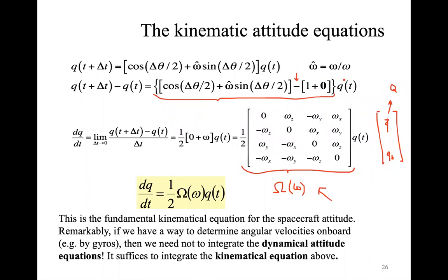So the gyroscope gives you important information where you don't have any information regarding, for example, stars or the Earth and Sun, because gyroscopes are always able to give you a measurement of omega. The problem is why we're not always able to use gyroscopes. Well, as we're going to see, gyroscopes are really affected by many error sources.